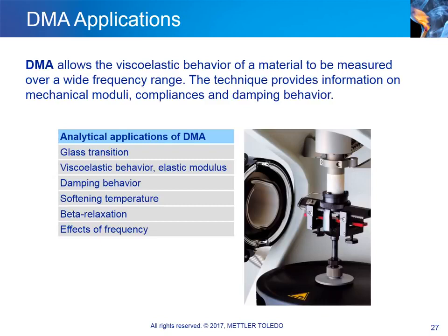The table on the left lists the main analytical applications of DMA. In general, DMA provides information about relaxation processes, such as the glass transition or secondary relaxations. Curing processes, pot or gelation time, melting, and crystallization are other application possibilities that can be studied by DMA. DMA is also widely used in a humidity-controlled environment to study the effect of moisture on material properties.